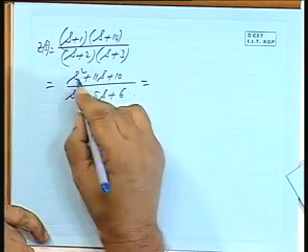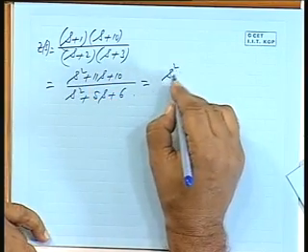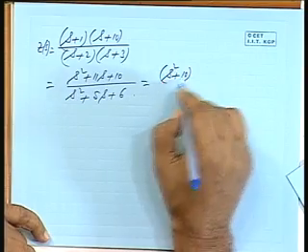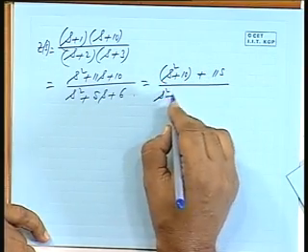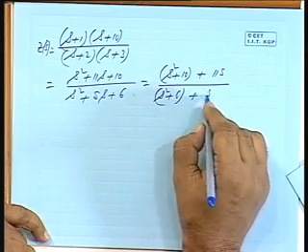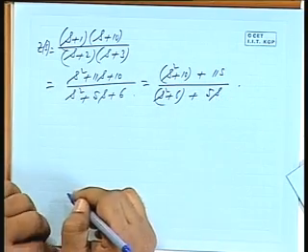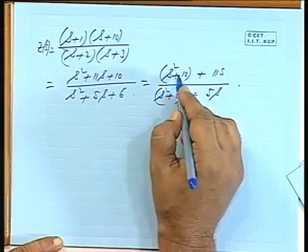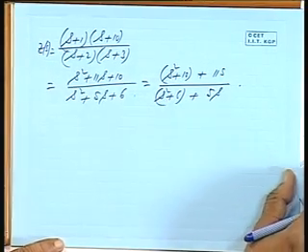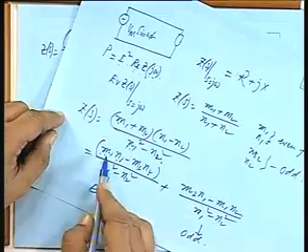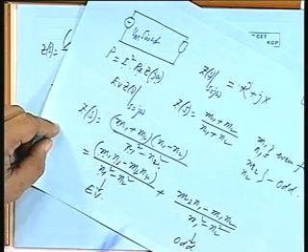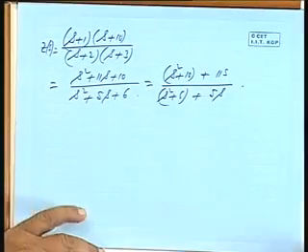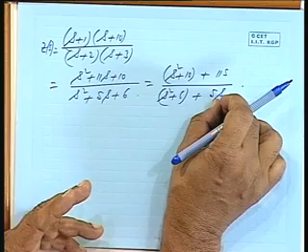So, what will be the even and odd part? S square plus 10 is the even part plus 11s, this is the odd part. Similarly, s squared plus 6 plus 5s. Okay. So, M1 N1 minus M2 N2 is to be tested for positiveness, because the denominator is always positive, that is what we have ensured. This square minus this square is always positive.